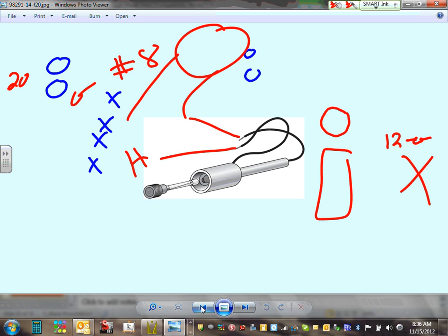So in the base, there will be an enclosure at the bottom of the pole, and you can open it and connect the wires. Where you connect the wires, you put the fuse right there. So if there's a short circuit, this will be dead, and you know that there's something wrong with it, either the lamp or it's shorted. So smart that utility maintenance guys open that little box and check the fuse is okay, and then the lamp is screwed up. You have to go fix the lamp.